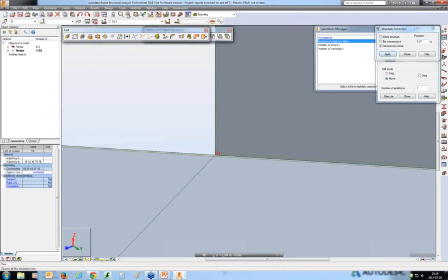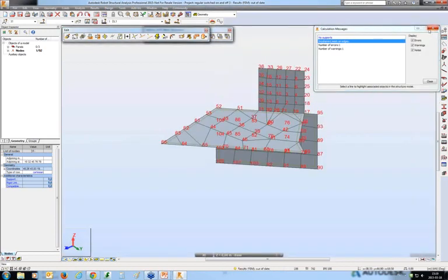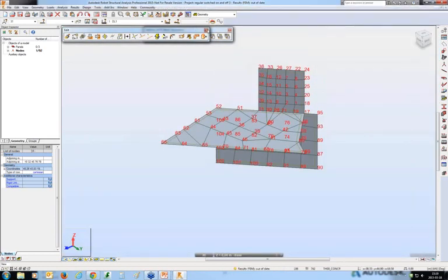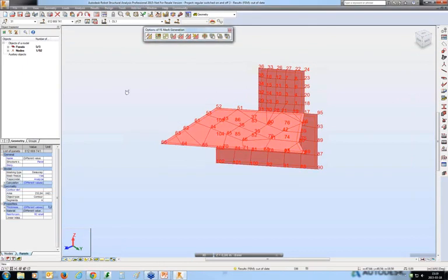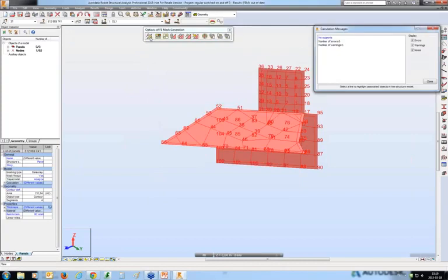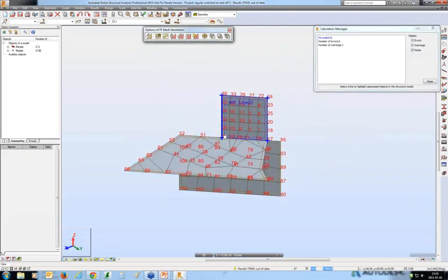What is important is to remember that you should freeze such modified meshes. So when you run model generation again, these meshes are not reset to the original settings. And as you can see, there is no incoherent mesh reported.